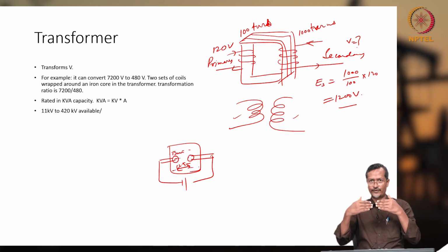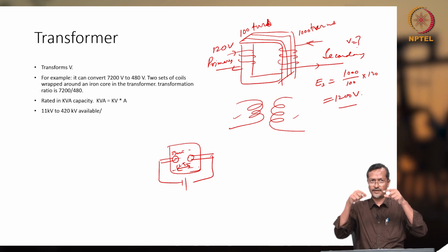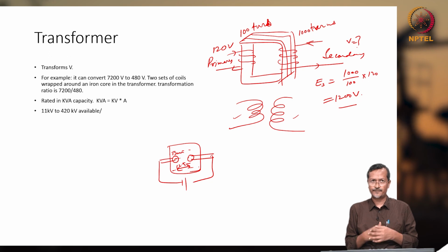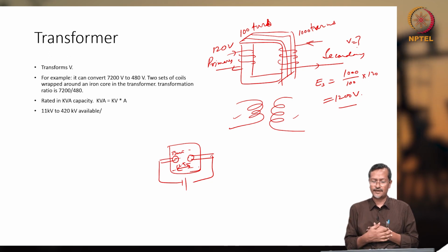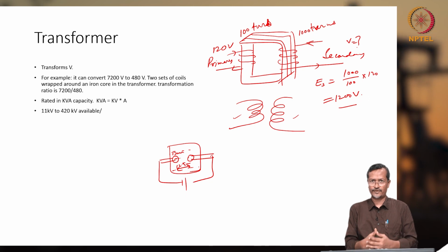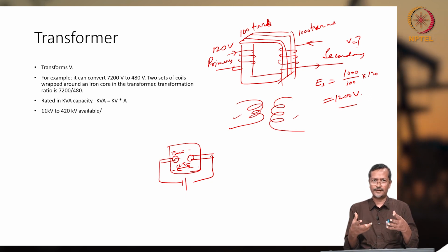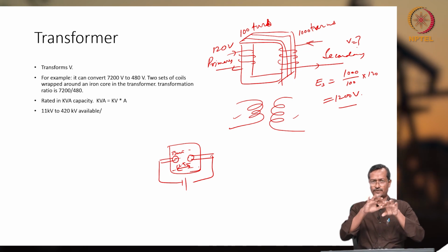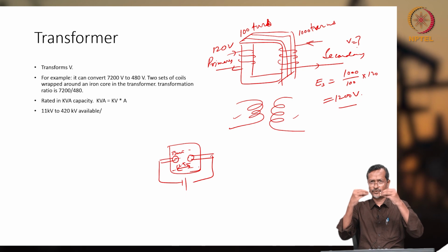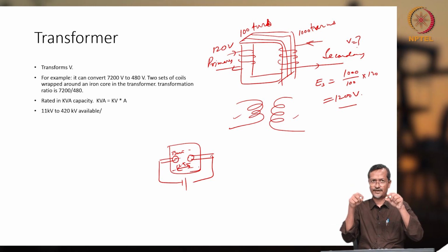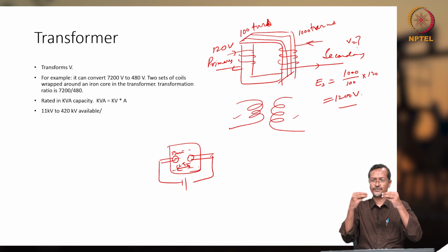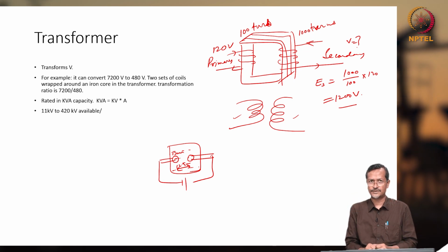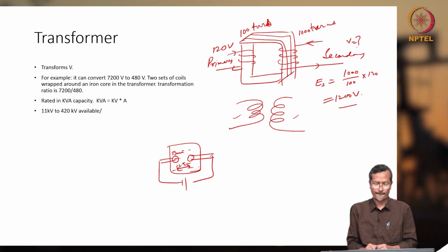Now, give a higher potential and see how much voltage it can withstand. If it can withstand, let us say, 33 kV or 40 kV, based on that you rate this dielectric fluid. Okay. So, the laboratory practice is a simple test, one box, 2 electrodes, and you apply different voltages and measure, and you can also reduce or increase the distance between the two. That way you can measure the quality of the dielectric fluid.